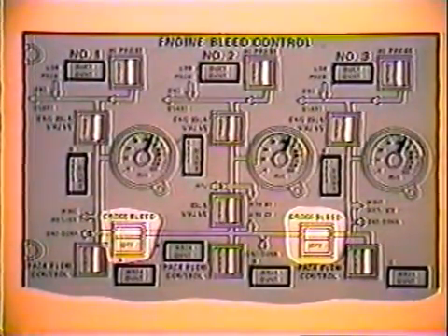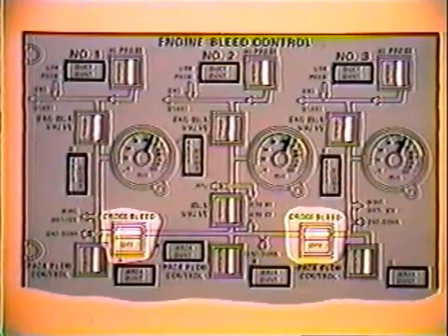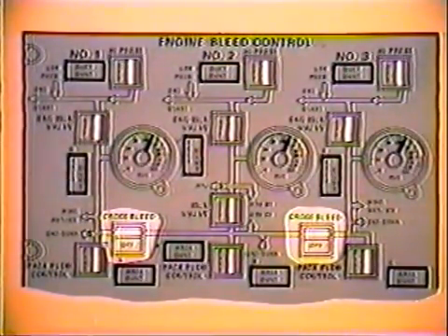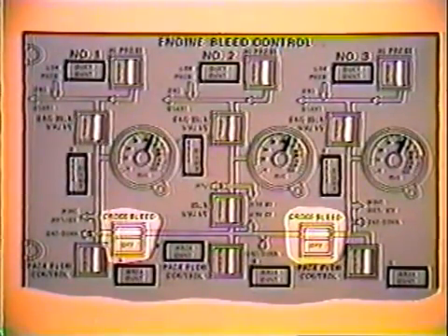The three bleed channels may be interconnected or isolated through the use of cross-bleed valves that are controlled with these cross-bleed switch lights. When the switch lights are latched in, the valves will open when pressure is available on either side of the valve. The flow bar will illuminate when the respective valve is open.